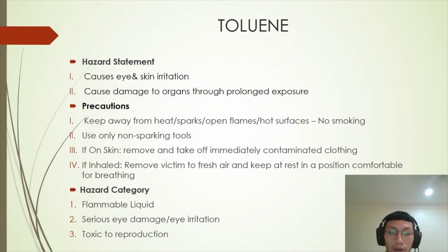If contact on skin, we need to immediately remove and take off the contaminated clothing. After that we need to rinse skin with water or shower. If toluene is inhaled, we have to remove the victim to fresh air and keep at rest in a position comfortable for breathing.